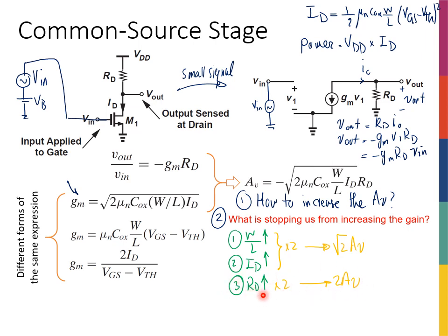As long as the area increase is reasonable, right? So if I have a 1 kilo ohm and I make it 1 mega ohm, then yeah, I'm going to be taking a lot of area on my silicon chip. So that's not really something that I like. But going from 1 kilo ohm to 2 or to 10, that's fine, right?